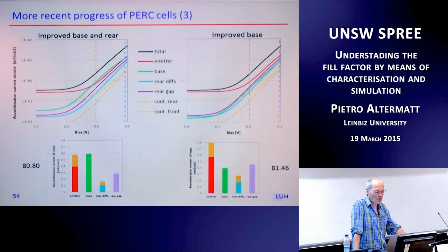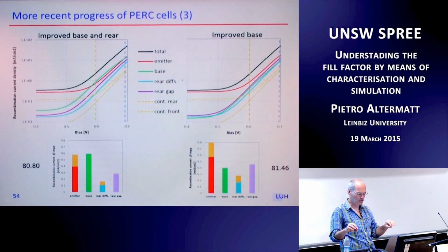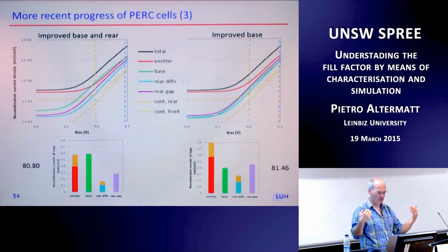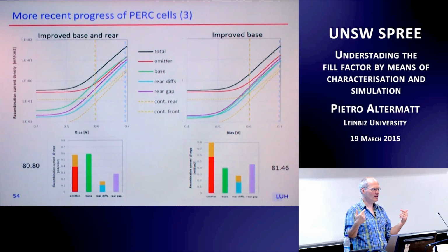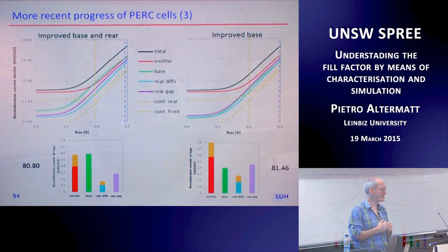So we do that, of course. We always etch back the cell so we know the base. We look at microscopy, SEM pictures of local structures at the back surface field, of the local back surface field. And then, when we are able to simulate the ideality factors, as I showed you, we first make a prediction of change this, change that. People go to the lab, do it. And if the predictions are correct, we start trusting our model, only then.